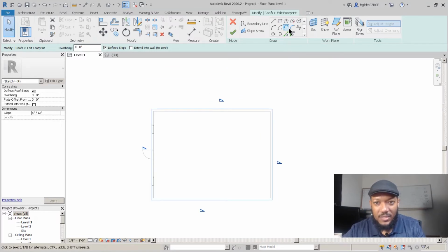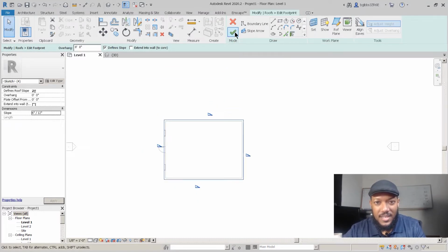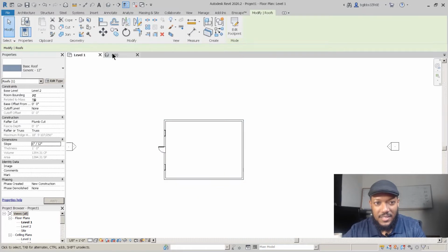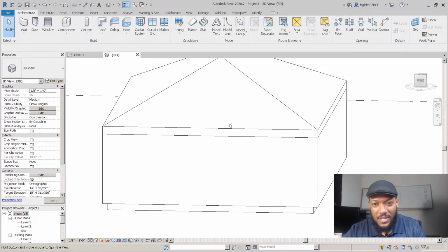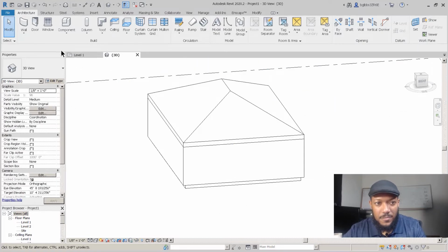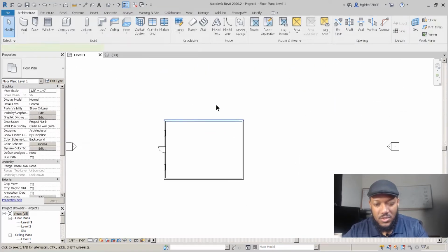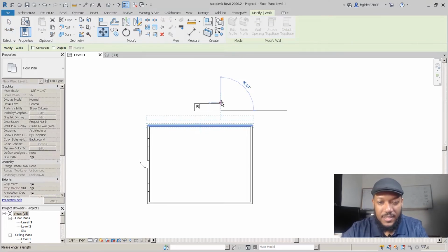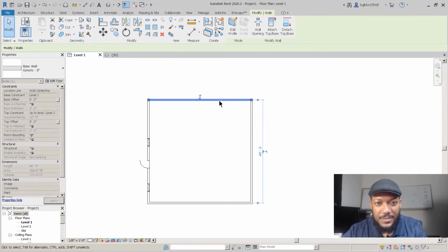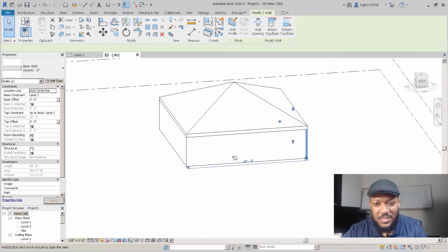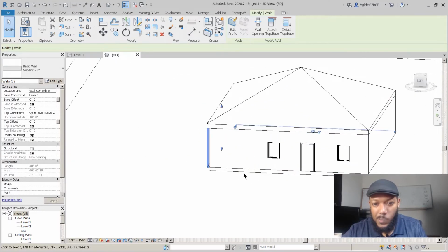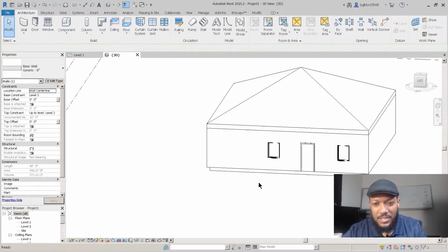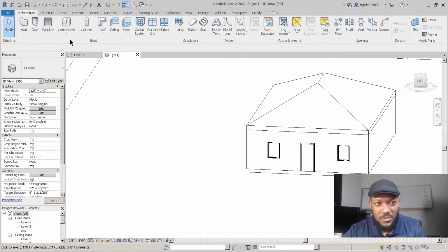And because I clicked with this button, you'll see that this is going to be constrained. And now we look at it: it's on the edge, it's already going straight down. So because I have these constrained, which is a great thing about Revit, if I just move the wall out, you'll see that the roof is automatically changed, and the floor as well. And we're going to undo, just pressing Ctrl Z or clicking right here, and you'll get back to what you're